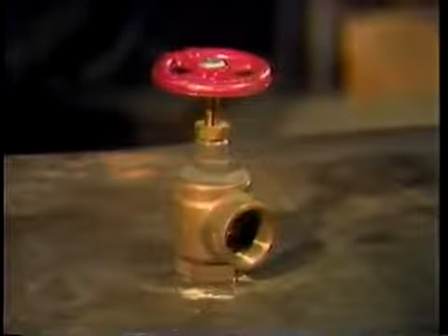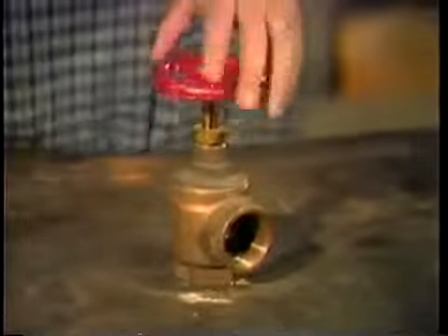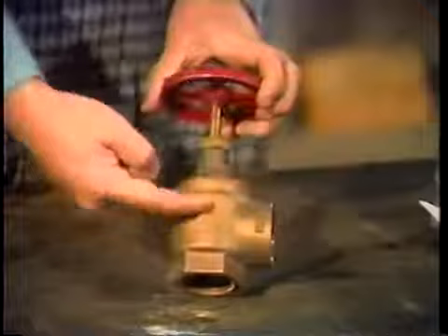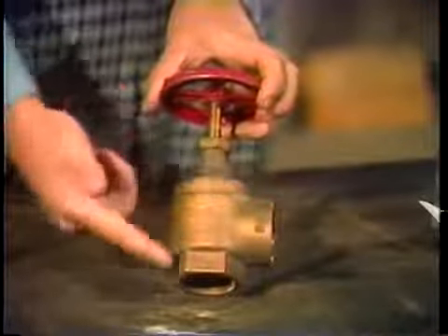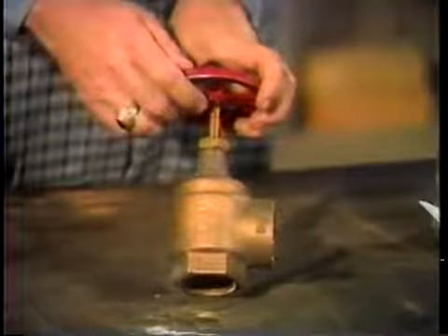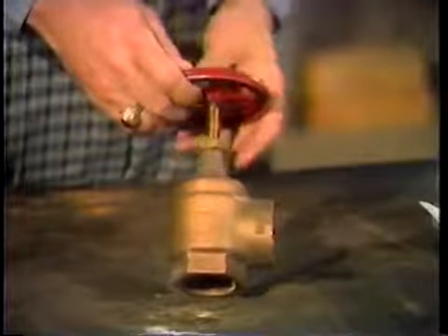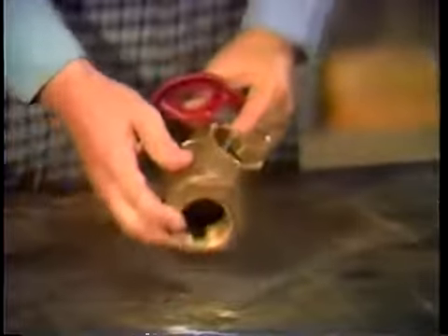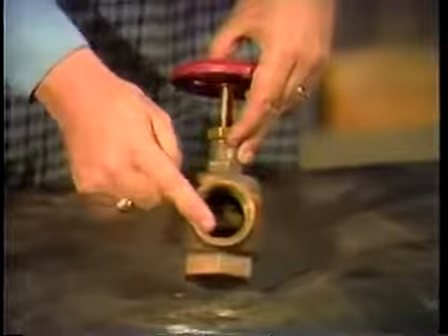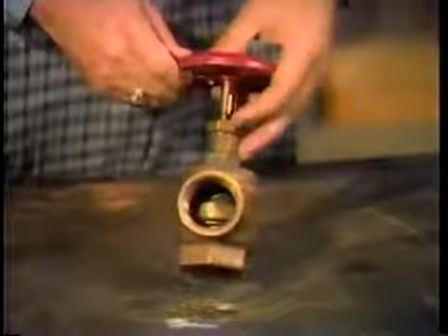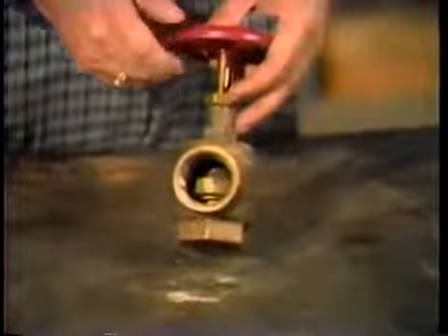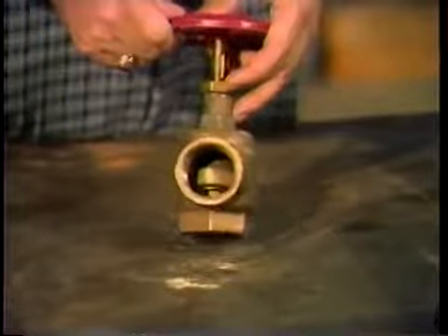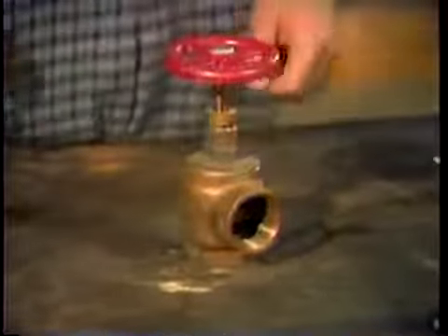Another body type is the angled globe valve. This design helps to eliminate the need for adding elbows to change the direction of flow, thus reducing the number of joints. The fewer the number of joints, the fewer points where leakage can occur. Now, both of these surfaces are built to provide a tighter seal for positive seating than is found on a typical gate valve. The shape and arrangement of the disc on a globe valve is varied depending on the type of surface it's designed for.